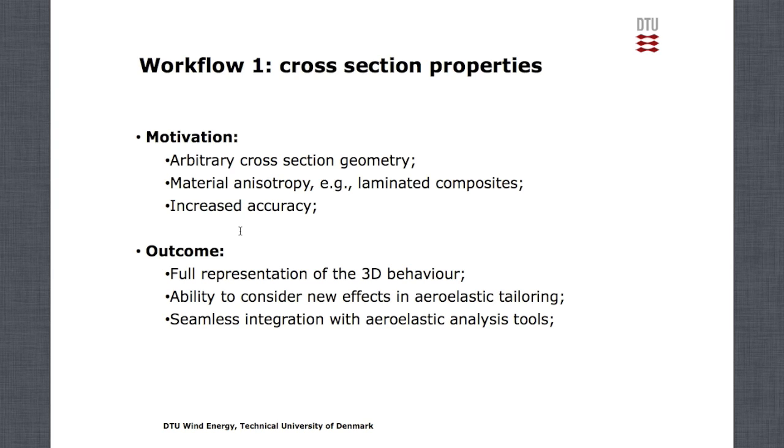The outcome is the full representation of 3D behavior of the blade, the ability to consider new effects in aeroelastic tailoring, and here one of the motivations was controlling the material properties to tailor the structural response and ultimately the aeroelastic response of the blade. And also, one thing that we have observed is that now you can have a seamless integration with the aeroelastic analysis tools. So now you have a continuous level of fidelity all throughout, from the structural model all the way to the aeroelastic analysis.